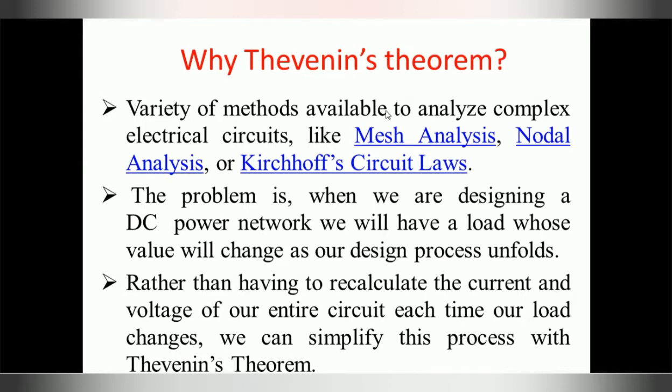But instead of performing the recalculation again and again, we can simplify part of the complex network into a simple network, and at the end of the simple network we connect the load. That is, we can connect any value of load at that end of the simplified network, and the calculation is simplified. For that purpose the Thevenin's equivalent circuit is used.